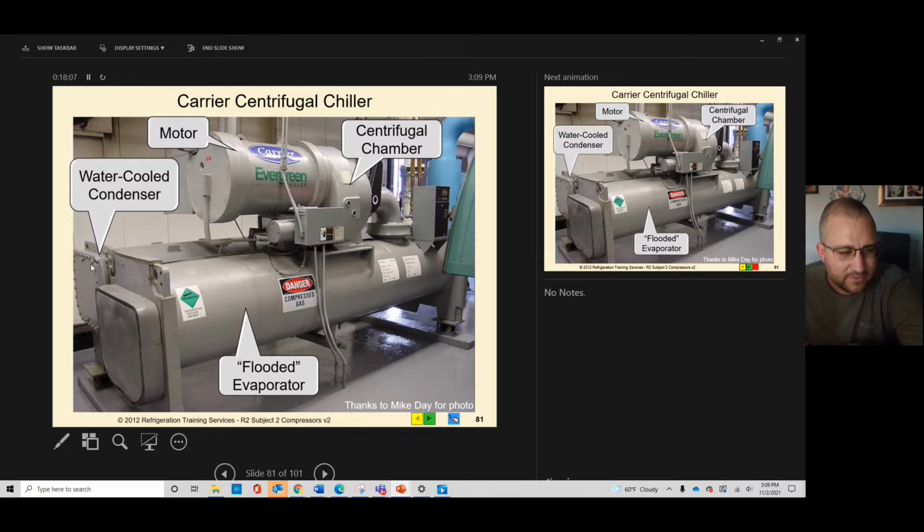So this, to kind of give you a little info on a chiller, this is a water cooled chiller. So it has two water barrels. So you've got refrigerant. In this one here, we had something very similar to this at MSU. And these take water in the ends. So you've got water that comes in, water that circulates through, and then water goes out. So you've got chilled water and you've got condenser water. So chilled water is the water that you're cooling the building with. So instead of piping refrigerant all over the building, they pipe water over the building. So they cool the water here, and then they send that water all over the building to cool it or use it in process equipment or whatever they're doing.